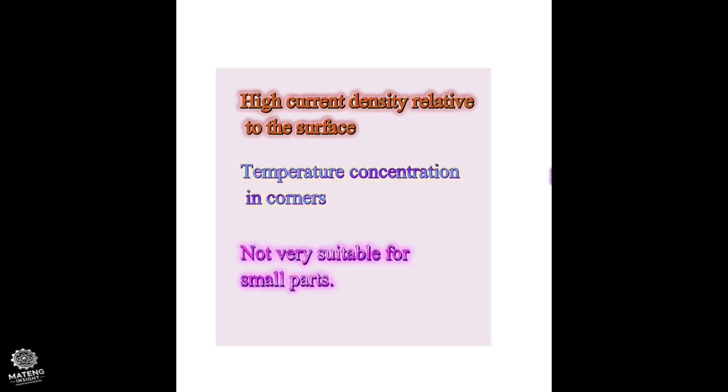Small and delicate parts are more sensitive to local tempering or distortion. For large-scale industrial components, these limitations are less critical, and using cold wall furnaces is more economical. For complex geometries, the edge effect may result in non-uniform plasma distribution.